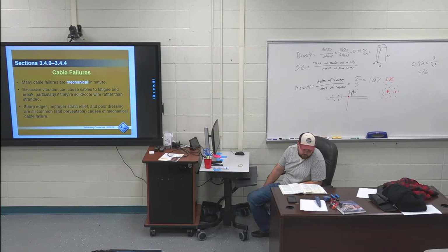All they're saying is you can measure DC resistance, and based on that resistance, all cables have a spec sheet that comes with them, or you can look up on Google, and they say what the resistance per foot is. So you can measure DC resistance, and based on that resistance, you can divide by the amount of resistance per foot, and that's how you can find it. So instead of using a time domain reflectometer or a TDR, you can use this loop resistance method to find it. And they go through the steps on how to do that for a pair of conductors or for coaxial cable. It's not something I've ever done, but it is an option.